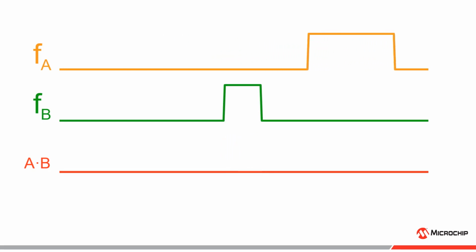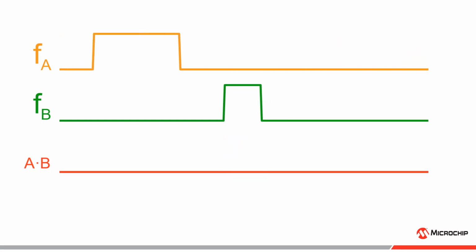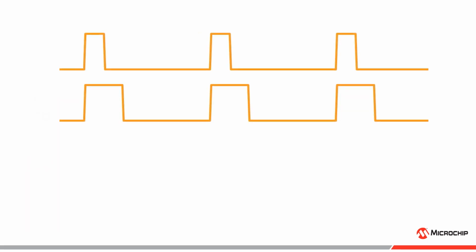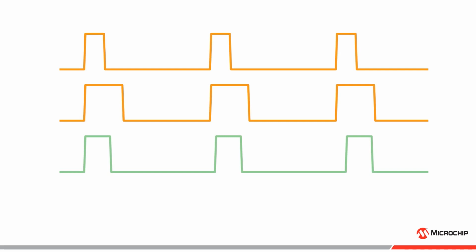In other words, the smallest duty cycle determines the maximum light intensity, and the larger duty cycle determines the length of the pulse. Since we want the heartbeat pulse to consist of two pulses with different light intensity, we have to add a third PWM signal. In this implementation, the first two signals, which we call A1 and A2, have the same frequency FA, but one has a small duty cycle and the other a larger duty cycle to achieve a small and a large pulse.